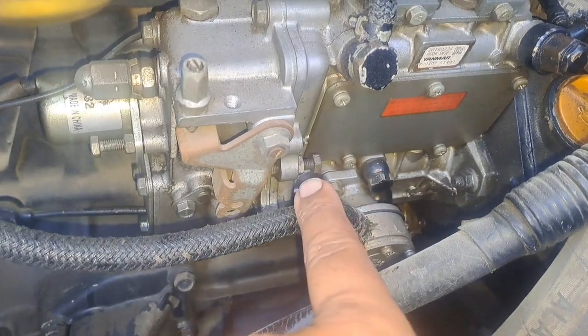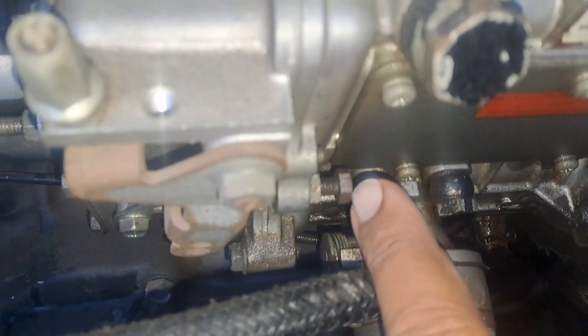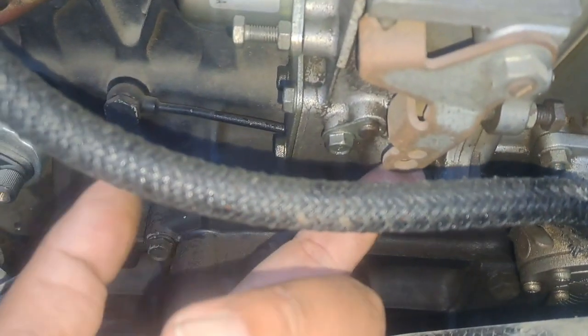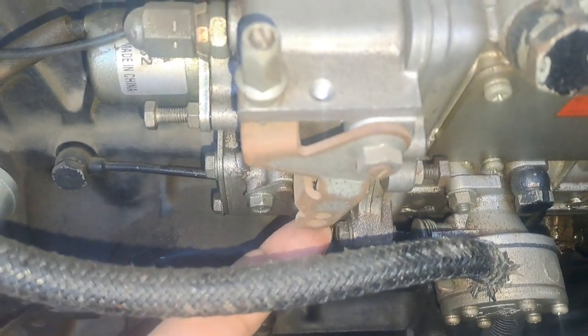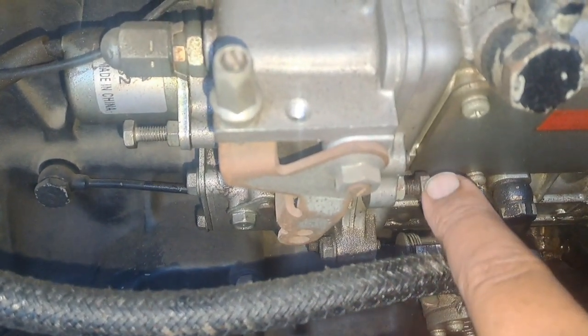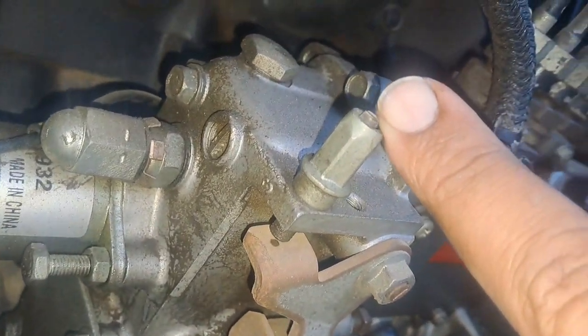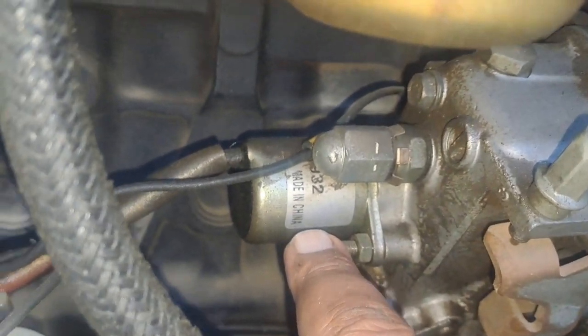If there is low frequency, you can increase by screw tight this one. Number 10 spanner. If you tight this throttle, it will come like this and speed will be increased. If you lose, it will go back, and here you have to tight this one. If you tight, it will not come up and down. And here is the fuel cutoff.